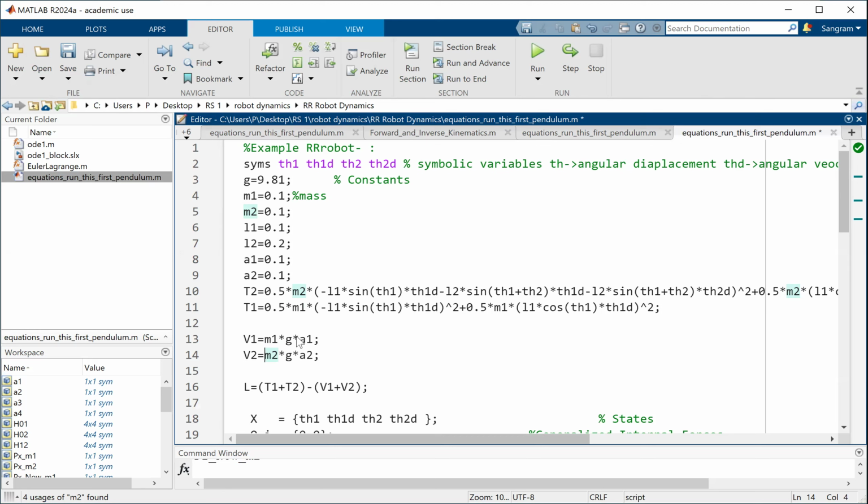That sometimes becomes tricky. You are welcome to try it, I did not try it, because you will have to replace diff theta 1 in parentheses t, comma t, which is a built-in MATLAB function, because diff is a MATLAB function, by another variable. So that requires overloading. But if you want, you can figure it out.